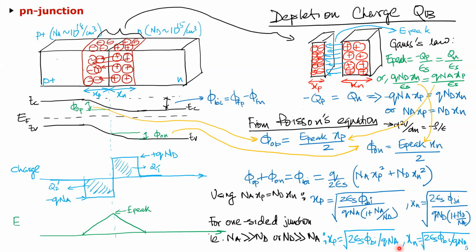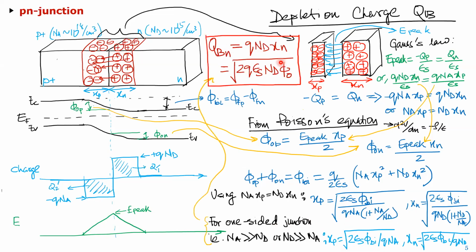Then you have this expression here, and you multiply that with Nd, you get the total charge inside it. That's why we did all this stunt, okay? So just remember this expression here. Inside a depletion, your charge enclosed is 2q epsilon s times the dopant concentration times the potential difference within that semiconductor between the two walls of the depletion area, like for example, between these two walls, or in this case, these two walls here, okay?